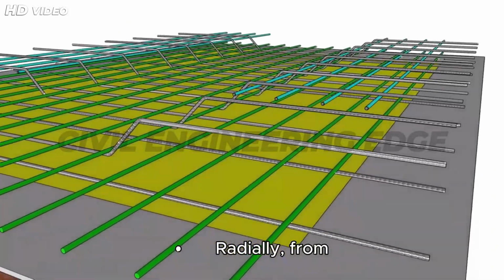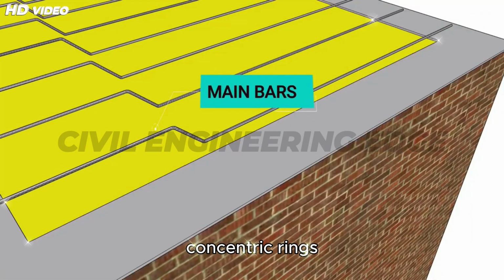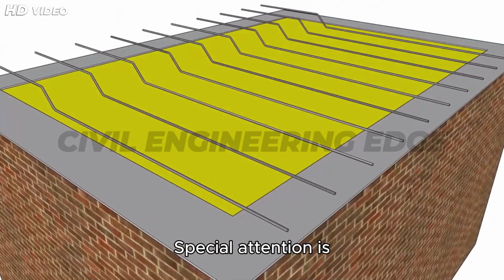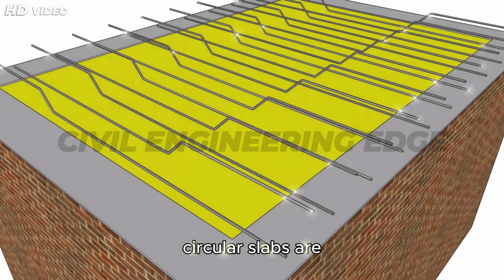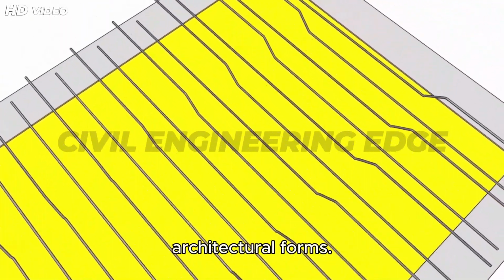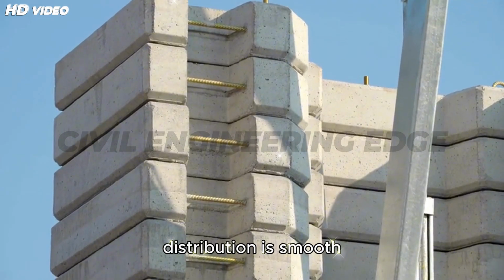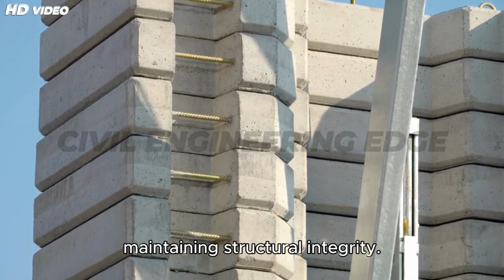Reinforcement is placed radially from center to periphery, tangentially in concentric rings. Critical points for maximum moments typically occur at the center and edges. Special attention is needed for edge detailing and support conditions. Although rarely used in common buildings, circular slabs are essential in hydraulic structures and special architectural forms. Proper reinforcement detailing ensures load distribution is smooth and aesthetically pleasing while maintaining structural integrity.